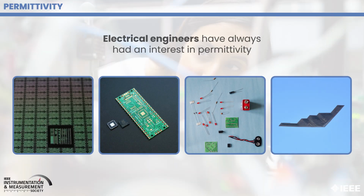Anyone involved in the design of semiconductor components, electrical circuit boards, or individual discrete components would have an interest in knowing the permittivity of the items that they're designing with. More recently, people designing low observable vehicles, stealth vehicles, would have an interest in knowing the permittivity of the material. Permittivity, or dielectric constant, has been shown to be an indication of other physical properties of materials.